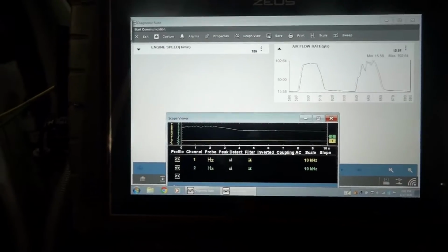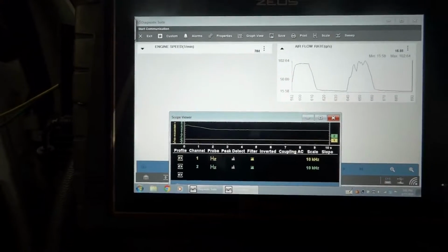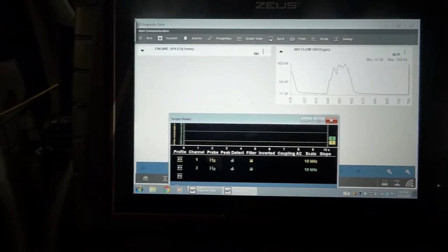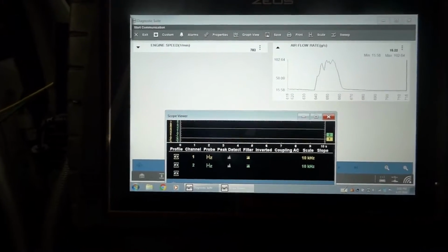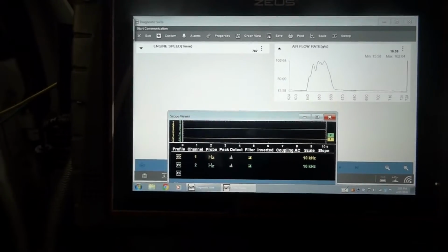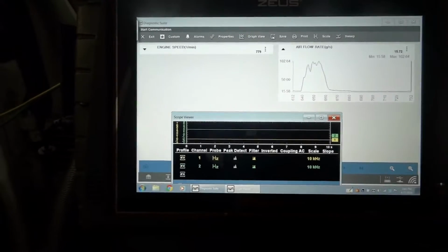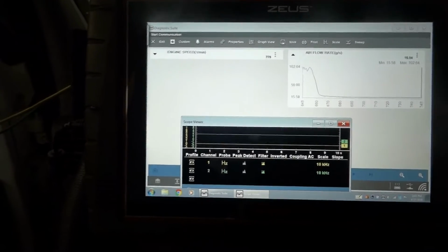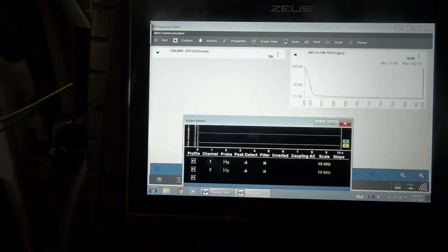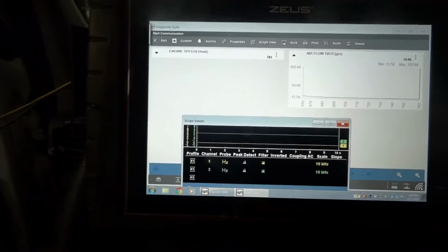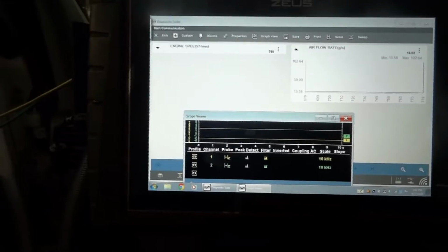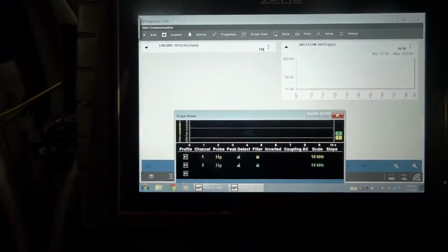Well, we have power, we have ground to our sensor, although the ground was slightly high, but I'm not really worried about that. Not as high as that it would really draw my attention. I wanna go under the hood again, and this time check all the tubes that go to the air cooler.